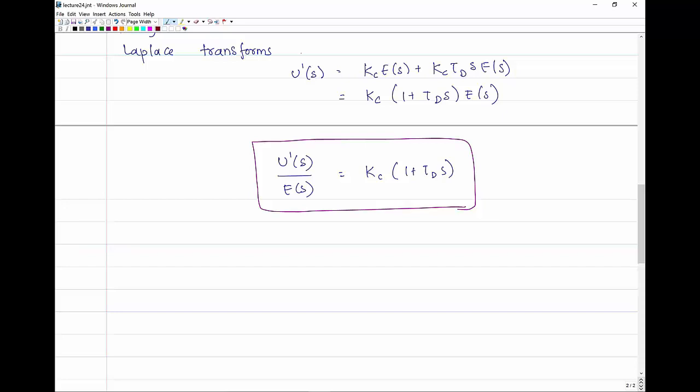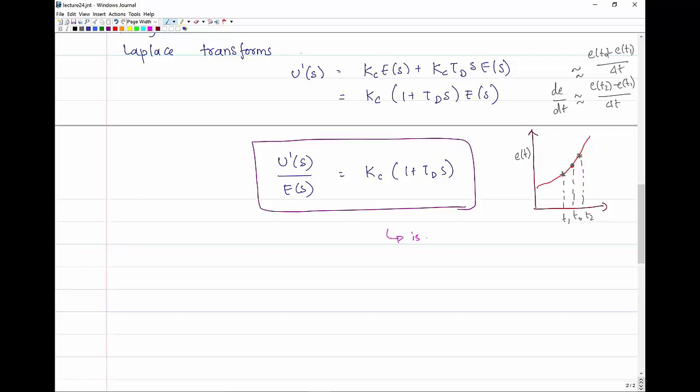And the reason for that is if you were to approximate the derivative at t0, you will have to use values of control error at t1 and t2. t1 is in the past and therefore you know that. t2 is in the future and therefore you don't know that. As a result, finding the derivative is not easy, and you have to use certain types of approximations of the derivative in order to implement the PD controller.